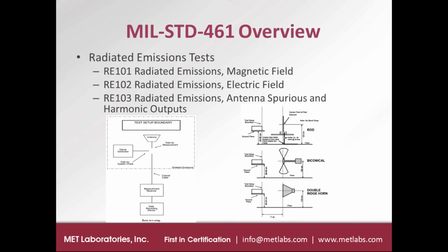And RE103 is an alternate test method for CE106. CE106 is the preferred test method. However, some EUTs have embedded antennas, or they have antennas that contain active circuitry within the antenna itself. And in order to test those designs, RE103 is provided as a test method there.